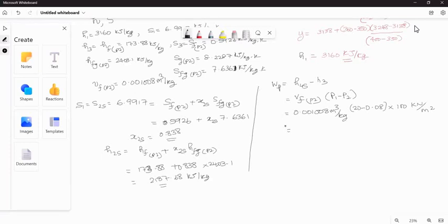That's why, because these kilonewton meter, now you will have kilonewton per kilogram. Then what is kilonewton into meter? That is Newton meter, which is joule. Again kilo is multiplied, then kilojoule per kilogram. So now this is the heat pump work input.